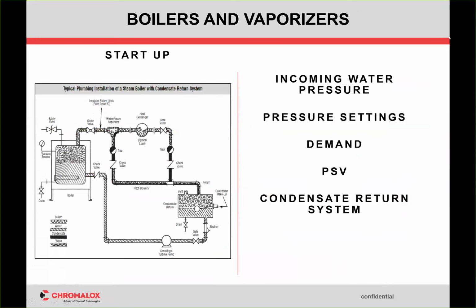Again, same thing as before. I know these drawings and even these data sheets we have are pretty much outdated, everyone on the call, but the technology hasn't changed. The boilers, the same thing with the startup on boilers. One thing I want to point out and make sure everyone understands: our boilers are controlled by pressure. You set a pressure on them, they'll trip on, they'll start heating. The vessel itself builds up pressure until it meets that point, and either you call for steam at that point and open up the valve and let the steam out and it continues to make pressure, or you don't and the elements turn off and it stops creating steam.